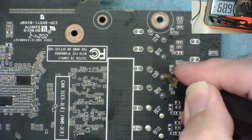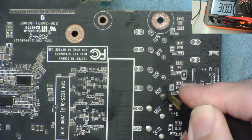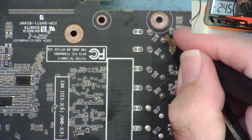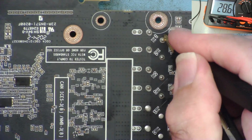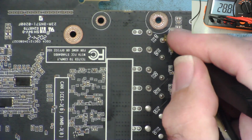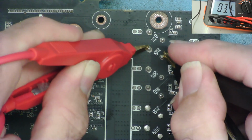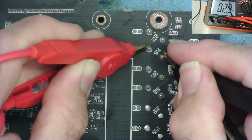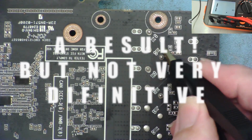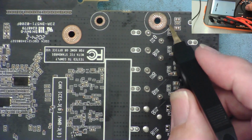What's this one reading? 29.8. Not much difference. What's this one reading? 30. What's this one reading? 301. So it seems that this first one, 28.3, is actually reading lower than all of the other ones. How much resistance are these? Oh yeah, the coils are reading very, very low, 0.029. It has very, very low resistance. But it looks like this one is the one that has the short to 12 volts, the one nearest the bottom of the card.